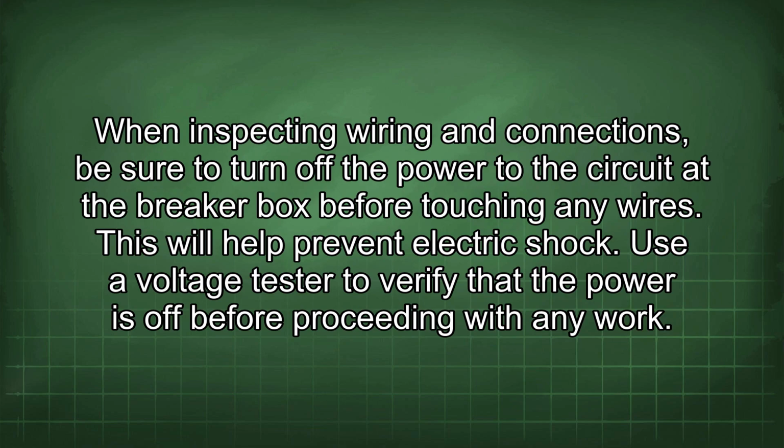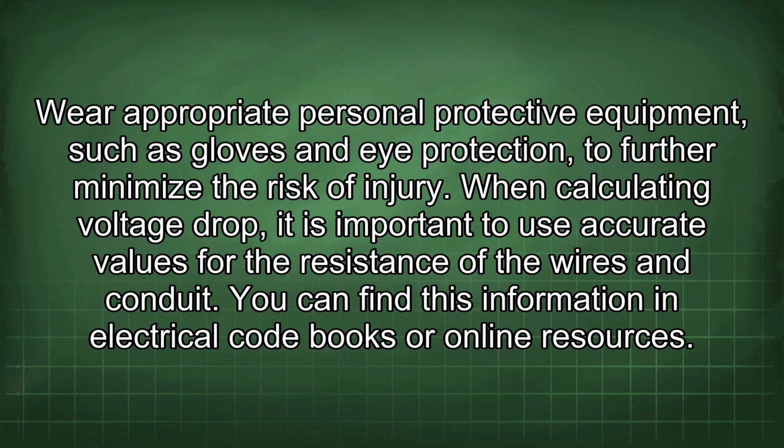When inspecting wiring and connections, be sure to turn off the power to the circuit at the breaker box before touching any wires. This will help prevent electric shock. Use a voltage tester to verify that the power is off before proceeding with any work. Wear appropriate personal protective equipment such as gloves and eye protection to further minimize the risk of injury.